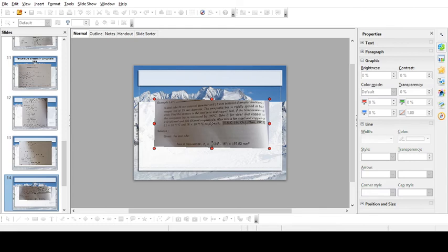So it is given that this is a hollow steel tube which has an external diameter of 24 mm and an internal diameter of 18 mm. It is enclosed with, it means a copper rod is inserted inside it, of diameter 15 mm. So this composite bar is rigidly joined at both the ends. Now if the temperature is increased by 190 degrees, we need to find the stresses in both the bars. Okay, so it is as simple as it is. All the values are given.